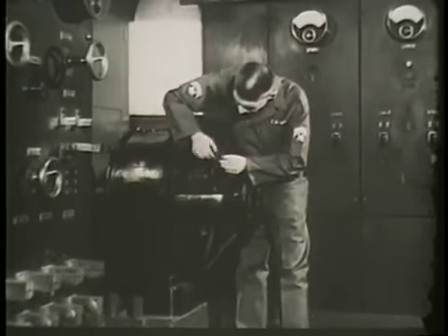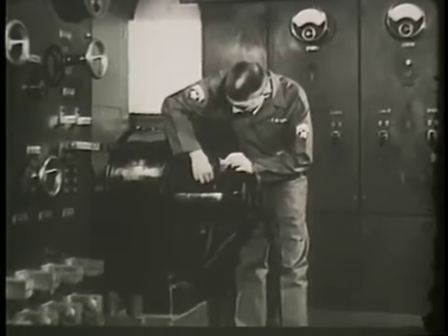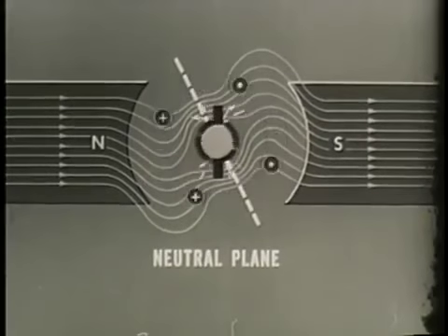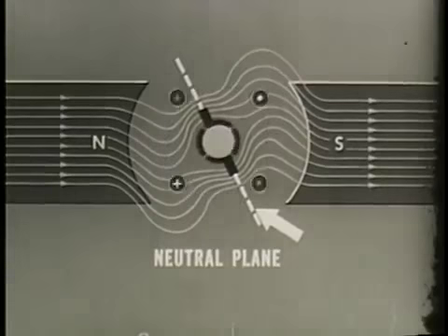This sparking can be prevented in one of two ways. One is by the adjustment of the brush position. The brushes are moved until they lie in the adjusted neutral plane.